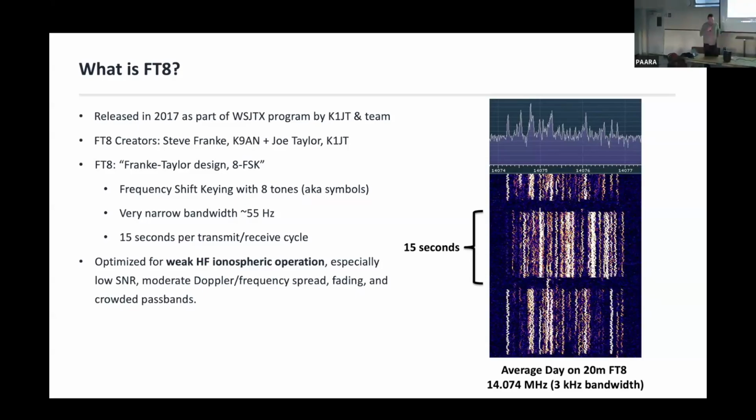There's a number of modes in there, but FT8 is just one of them. It's created by Steve Franke, K9AN, and Joe Taylor. FT8 stands for Franke-Taylor Design, 8-FSK. It's frequency shift keying, so there are 8 tones or symbols, as they're called in the DSP world. It's very narrow bandwidth, like 50 hertz. It can even be narrower than CW. You're able to hear it a lot more faintly.